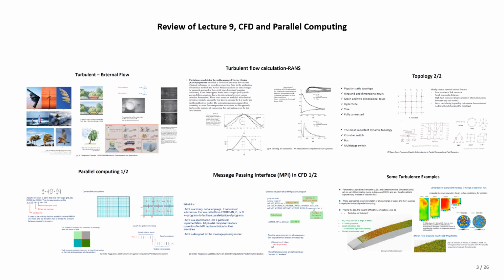Then we had some turbulence examples with RANS, LES, and DNS, and some comparison regarding the cost and also the speedup, and some drawbacks of RANS. For example, in a case with a change of geometry, RANS did not capture the change of the geometry, so this is one of the drawbacks of this approach. We recognized that in some cases we need to use LES or DNS to calibrate the RANS solution to get better accuracy.